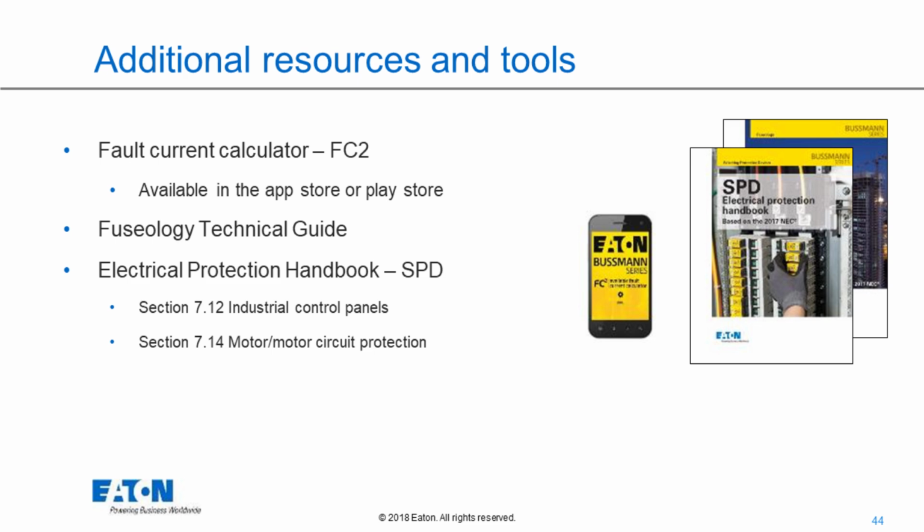For a contractor out in a plant somewhere, if he knows the information on the transformer and the conductors, he can put that information in and find the available fault current really easily. Then he can print out a label of what the fault current is on the specific equipment, and that label can be attached to, say, service entrance equipment that requires a label with available fault current and the date it was calculated.